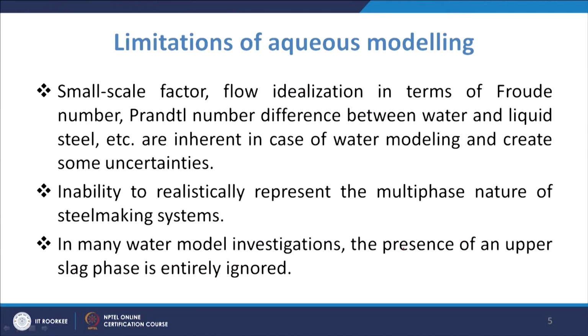Small scale factor, flow idealization in terms of Froude number, Prandtl number, difference between water and liquid steel, etc. are inherent in case of water modeling, and create uncertainties, because if you look at the physical properties of water and the steel, you will have differences in these number values, and they are going to inherently cause certain kind of uncertainties in the case of aqueous modeling, when we are taking water as the working fluid.